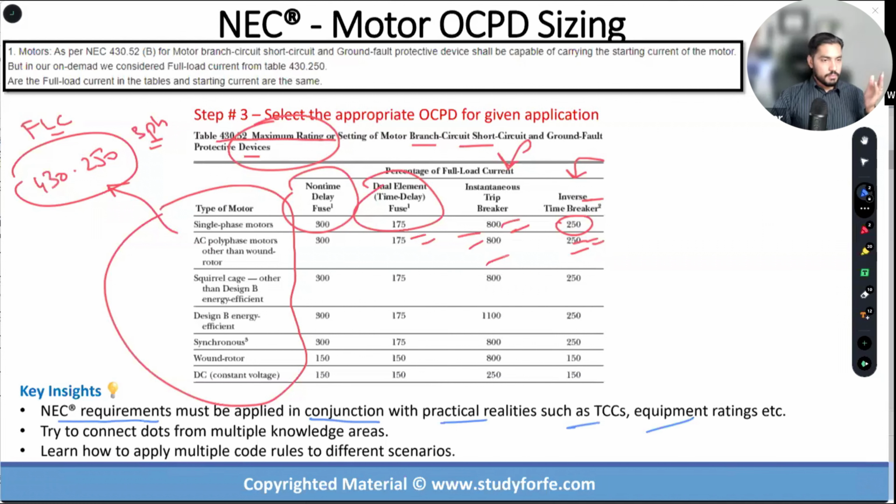regarding the type of cables that you're using, the distances that you can separate the VFDs from the motor, and whether there's a requirement for a line reactor, a load reactor. They may talk about the SPD requirements, especially for the VFDs. Sometimes they're built in. So this is bare minimum. I want to keep on reminding you again and again. NEC is the bare minimum requirement. There's a lot that you have to do above and beyond in most of the cases.